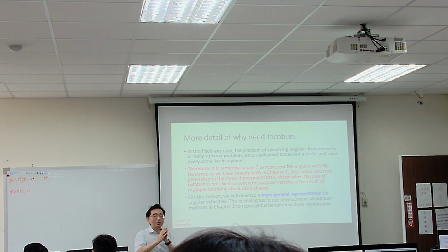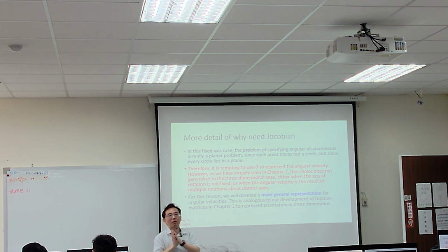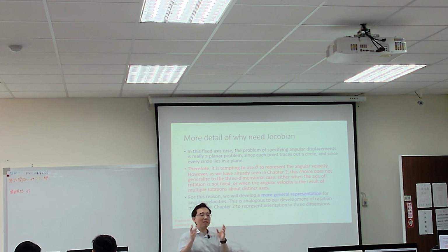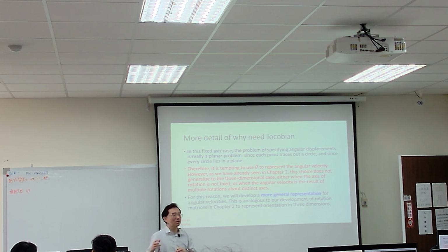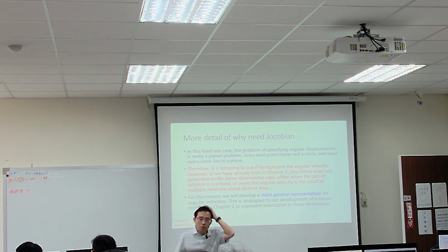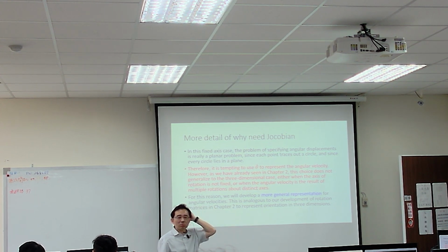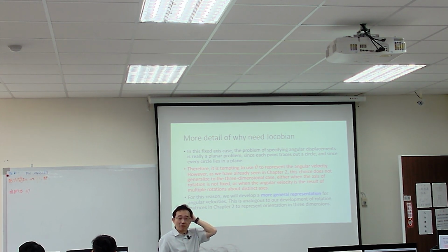But the angular velocity of this one joint is not produced by only one angle, because it multiplies at least two rotation matrices together, no matter whether you multiply zero or non-zero terms. So it's a compound result. If you want to control the speed, I don't know which angle I should control. There are two. So how can I control the final compound angular velocity?